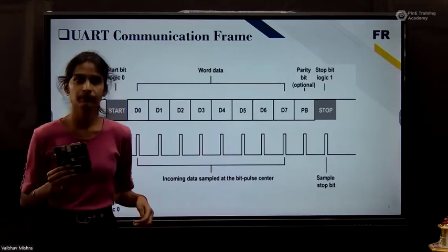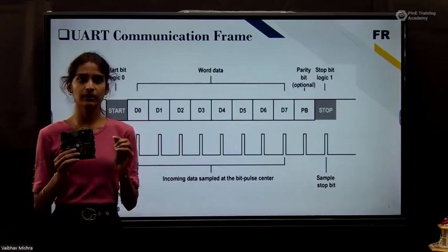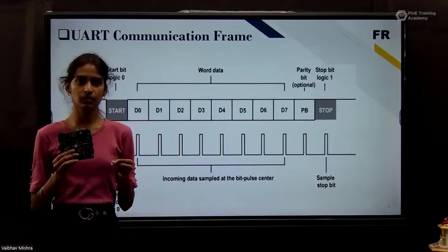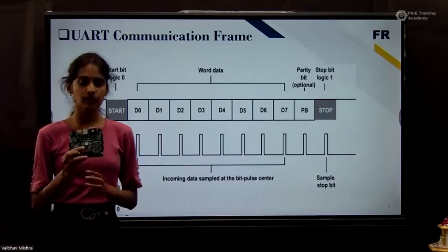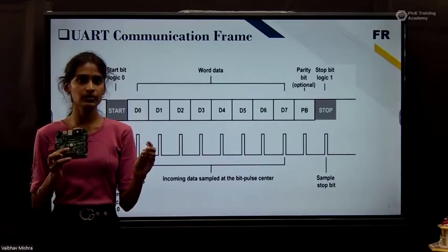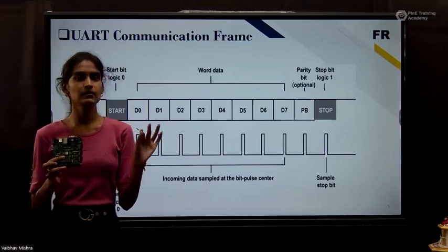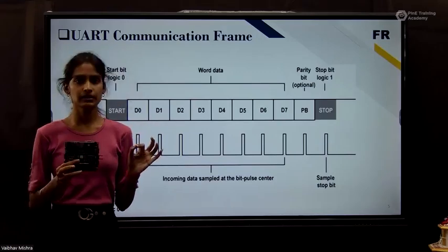So what we need is a jumper cable. One end of the jumper cable is connected to any pin of the PMOD port. Through this end of the jumper cable, our input data is transmitted serially, and through the other end of the jumper cable, we receive our serial data again from the PMOD port. Now the connection is done.